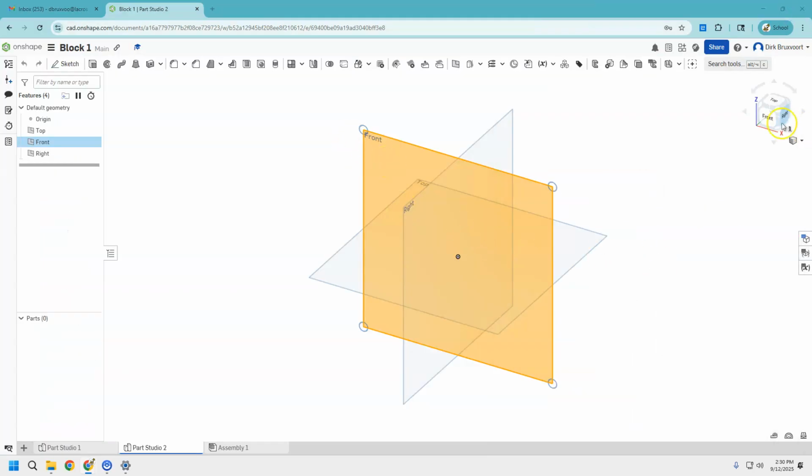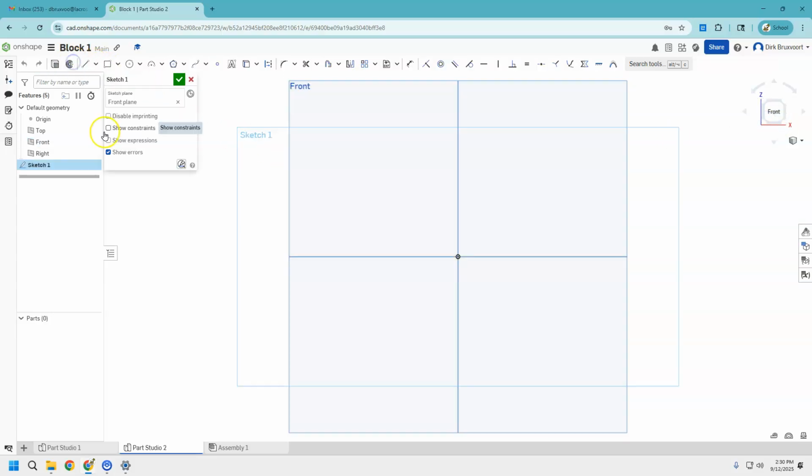What I'm going to do, front, zoom into it, sketch on that front plane. Okay, sketch says front plane here. We're drawing in there. That's good. This time I use the rectangle tool. I'm going to click on my origin. I'm going to draw, click. Automatically makes a rectangle. It's grayed, it's solid, better than trying to draw a bunch of lines. Go back to dimension. This cube is going to be 2 inches by 2 inches, okay, 2 by 2.